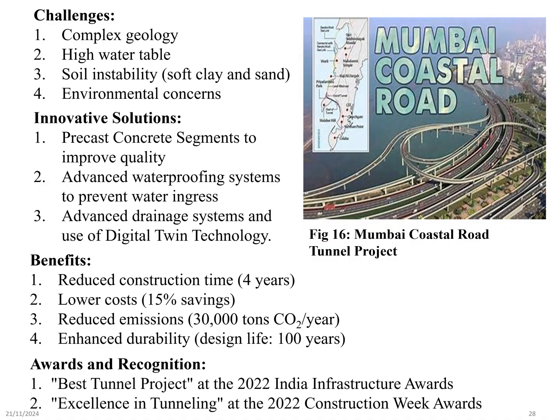Challenges faced: the tunnel had to navigate through varying rock types. Managing water ingress was crucial. Soft clay and sand posed significant challenges. Ensuring minimum environmental impact was a priority. Innovative solutions: precast concrete segments improved construction quality. Advanced waterproofing system prevented water ingress effectively. Advanced drainage system managed water efficiently. Digital twin technology was used for real-time monitoring.